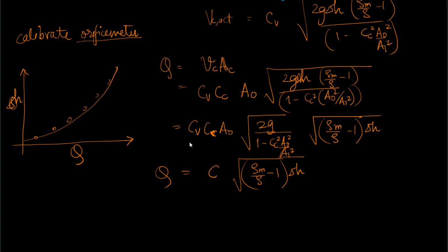All this is valid as long as these ad hoc coefficients are not too deviant from the value of 1. Once they start deviating significantly from 1, that implies that the idealities have been lost significantly, meaning there are enough viscous losses or recirculation losses in the flow situation to render this entire experiment futile. You have to redo it with a different orifice, which will obviate some of the issues arising from this particular orifice size.